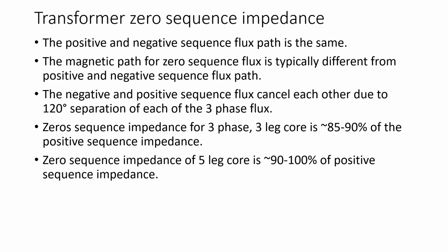So if you take a three-phase core, for instance, and assume this is a core, this is the middle leg, and obviously the coils are somewhere here, wound around the core limbs. For core form, the windings are cylindrical.